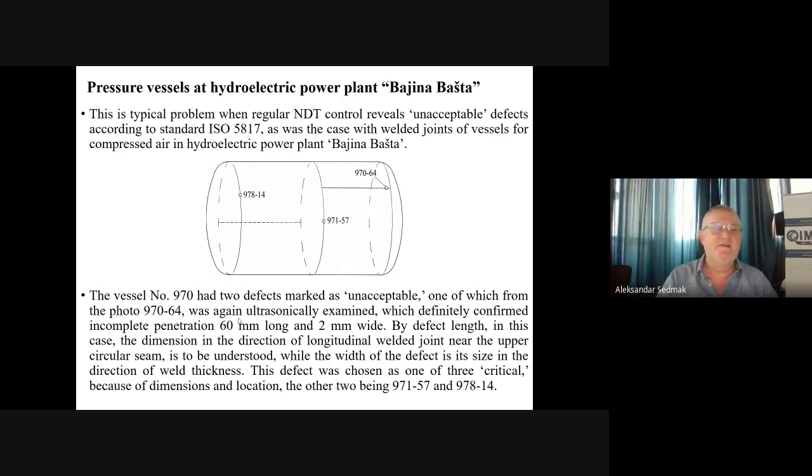That was the surprise, because all evidence indicated that these defects were there from the very beginning. First of all, there is no fatigue. Then there is practically no corrosion and any other mechanism of potential crack growth. This is a typical simple static case and simple geometry. A cylindrical pressure vessel, no inlets, outlets, nothing close to these defects.